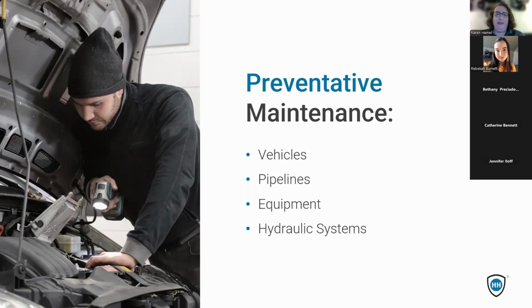We got the bill, we paid the bill, and we never really had accounted for what they were doing in the forms of preventative maintenance. Were they replacing seals? Were they catching leaks and drips? We really didn't know. So we actually changed our contract to kind of give an account for all of the tasks that they were performing so that we knew what was going on with those machines. We knew when seals were replaced. We knew when they had found a leak or a drip within a system. We knew when the different hoses were replaced, and we hadn't thought to really do that before.